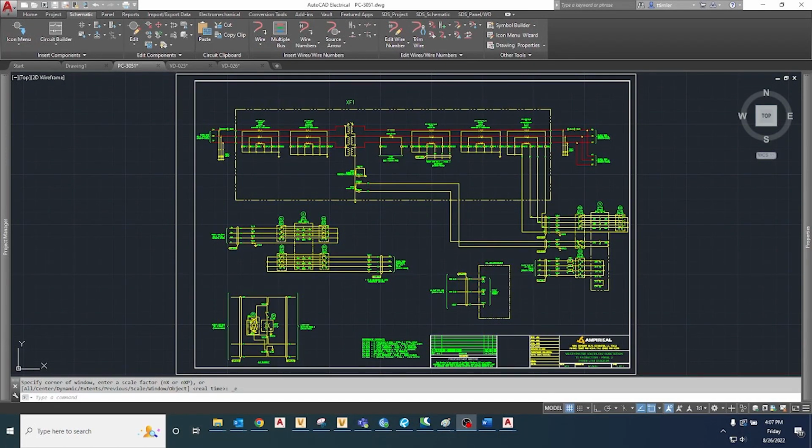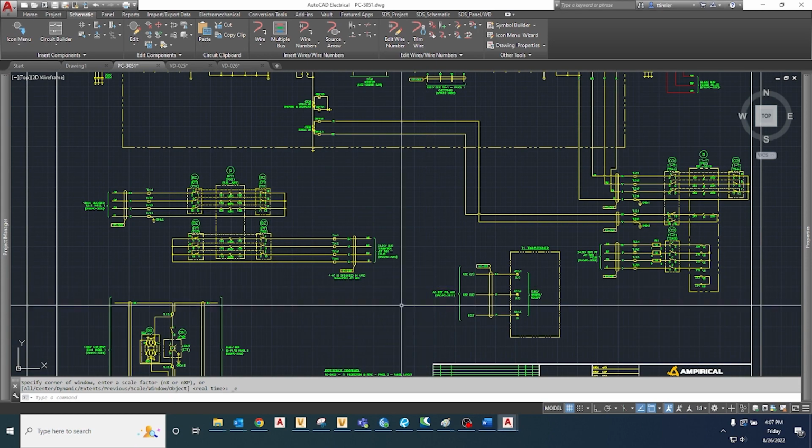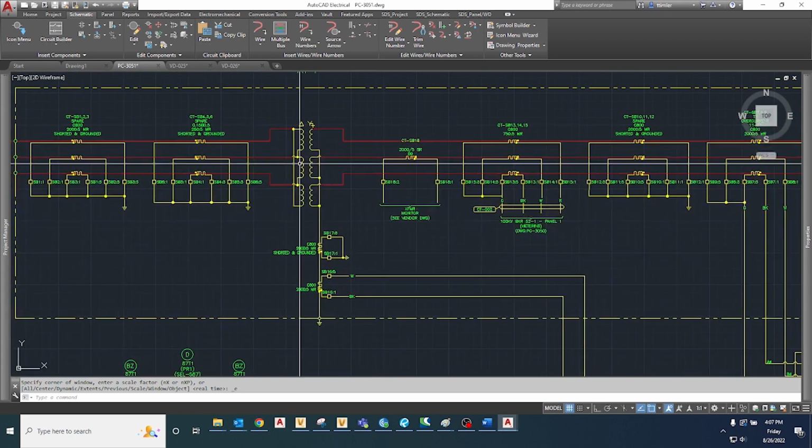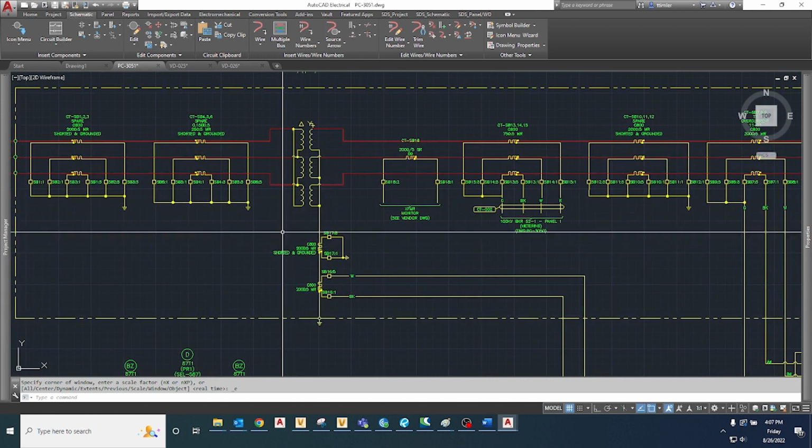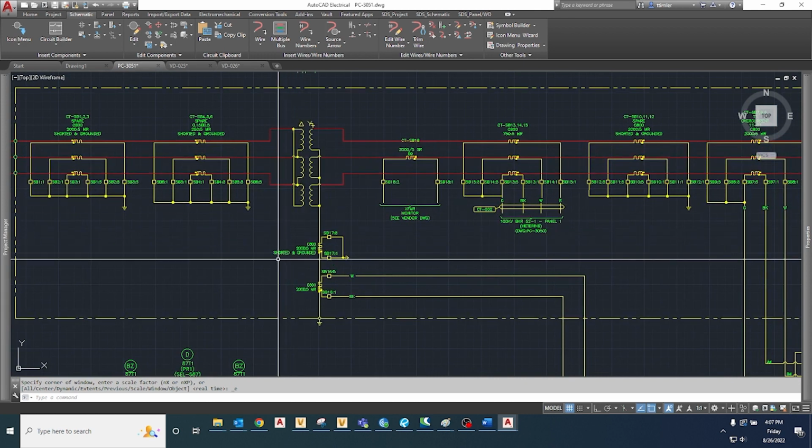This is a 3-line transformer symbol I created and inserted during our last session. Since the transformer symbol can represent a variety of different transformers, there is no default information on the drawing. Instead of forcing the user to enter information into this symbol and other symbols that he inserts, we can embed that equipment information into the catalog database and let AutoCAD Electrical populate the symbol data for us.